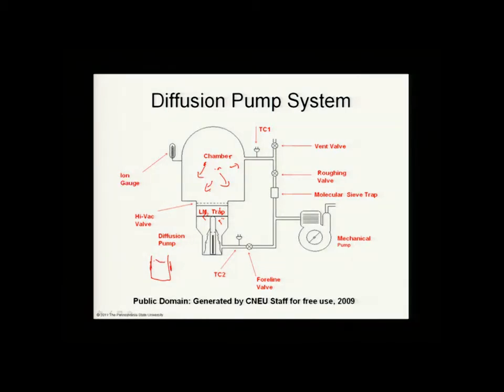Here the glass of cold water is liquid nitrogen, and the water, quote unquote, is not water, it's liquid nitrogen. And the coating on the side, we'd like to be oil molecules so they don't get up into the vacuum chamber. We're pumping on the system with a mechanical pump so that when the molecules are here, and they're detraining, if you will, we capture them and pump them out. And you can see the different valves used to control this.